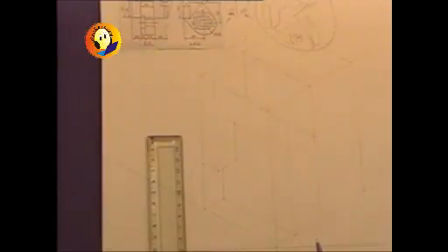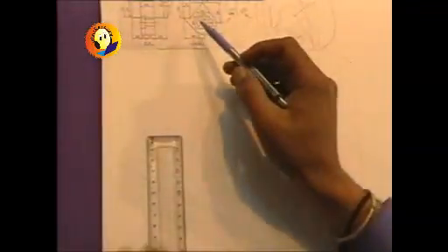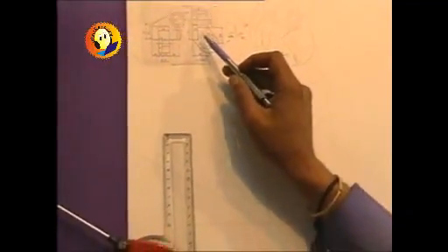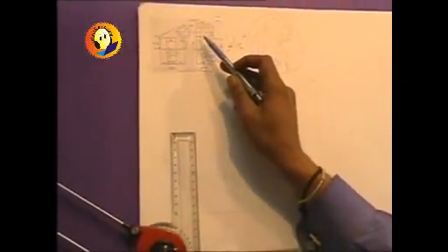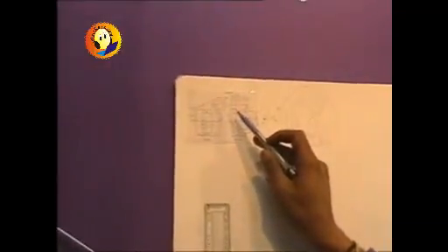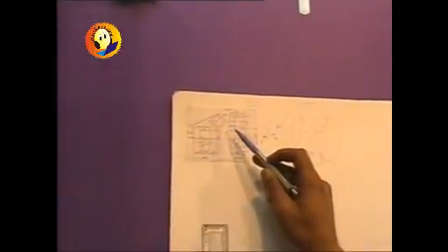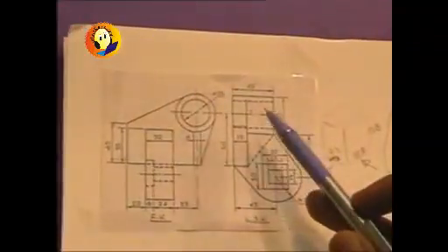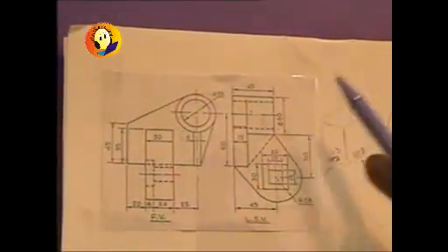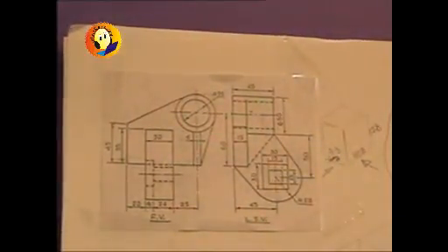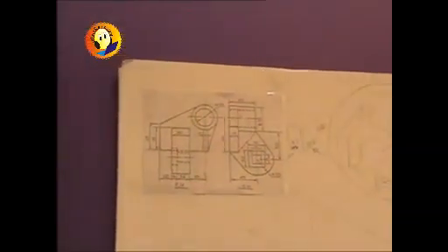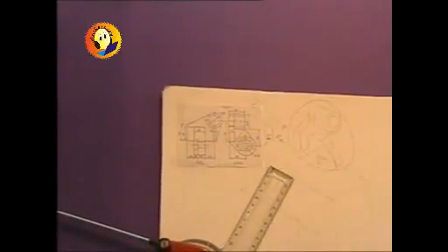Now we will shorten the box that is required for the cylinder, because cylinder is not till the full length as such as seen in the side view. The cylinder is having a length as 45 starting from back face, and so we can just shorten the block which we have drawn for the cylinder and draw it of length 45 only.